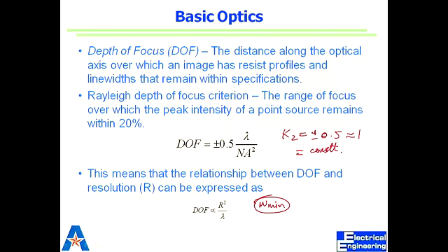If we don't get it exposed, what do we call that? Underexposed. How is an underexposed feature going to show up after development? You'll still see resist there in that feature. It will be exposed maybe halfway, maybe 90%, not all the way, so you will still have resist left behind. You might keep on developing, but after a certain thickness the resist is not exposed at all and is not going to dissolve. If you keep developing more and more, yes, it will dissolve, but then you will be opening your walls up. That's what is called over development.